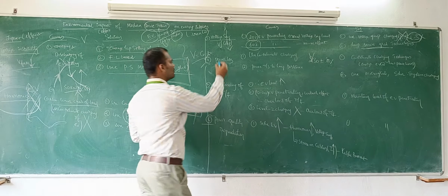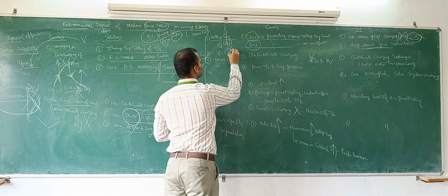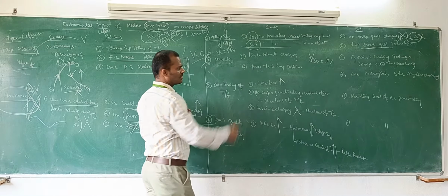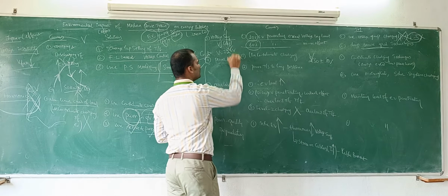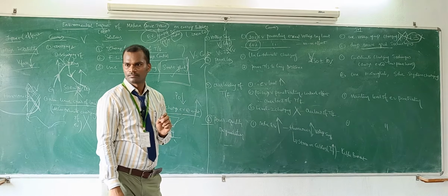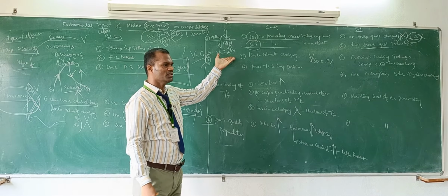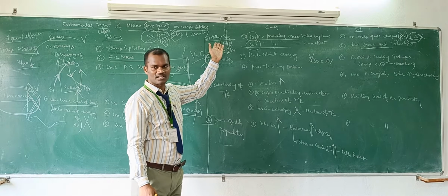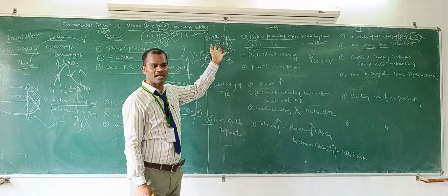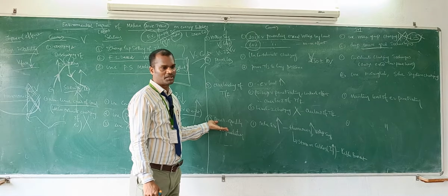So, what does voltage sag mean? You see here, this is 230 volts. When you connect this fast charging L3 charger, this voltage will fall down to 220 volts. What happened from 230 to 220? Voltage has been decreased. Due to this decrement, it struggles with voltage sag problems, which are called power quality problems.